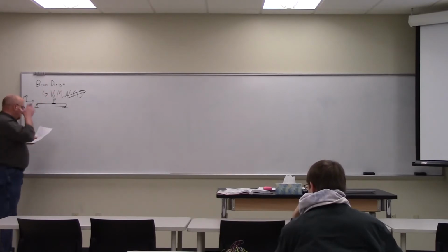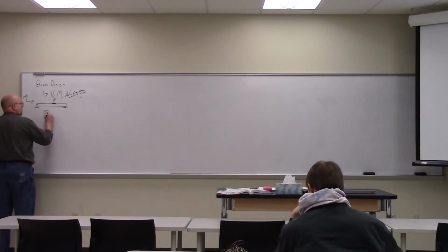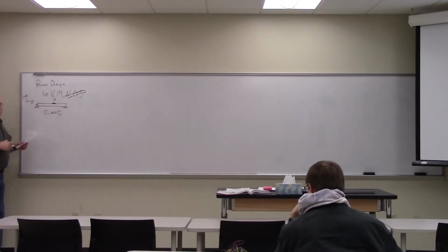So, sigma x, in this case, is still going to be much greater than sigma y at the point of application, so that we effectively only focus on the x component, the components along the beam. Okay, we're not worried about the sigma y that comes from that lateral load.